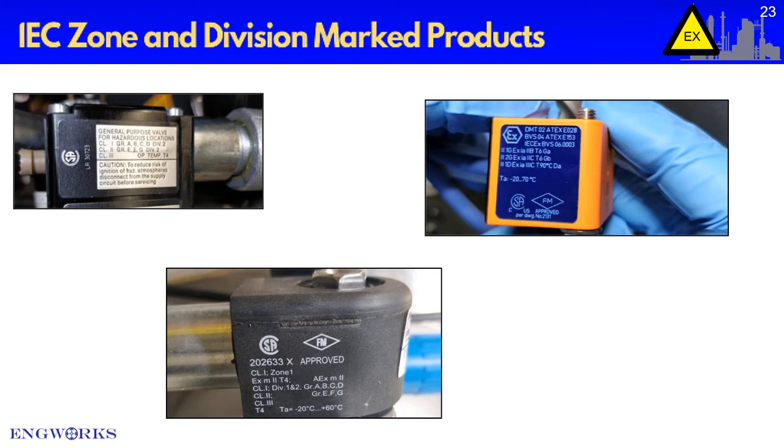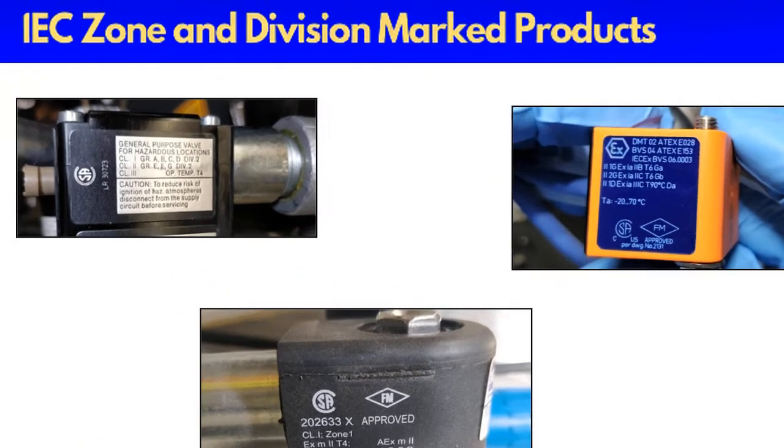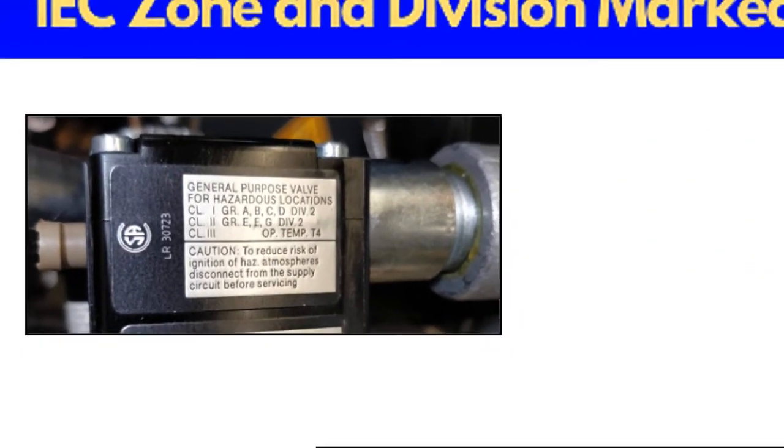As you can see on your screens, the two marking systems are very different. The zone-based marking system identifies the method of explosion protection incorporated into the product. The division-based marking system identifies the end classification where the equipment may be installed. In both cases, the markings must be interpreted to determine if a product is suitable for installation in the defined classification. This is an example of a division-marked product.